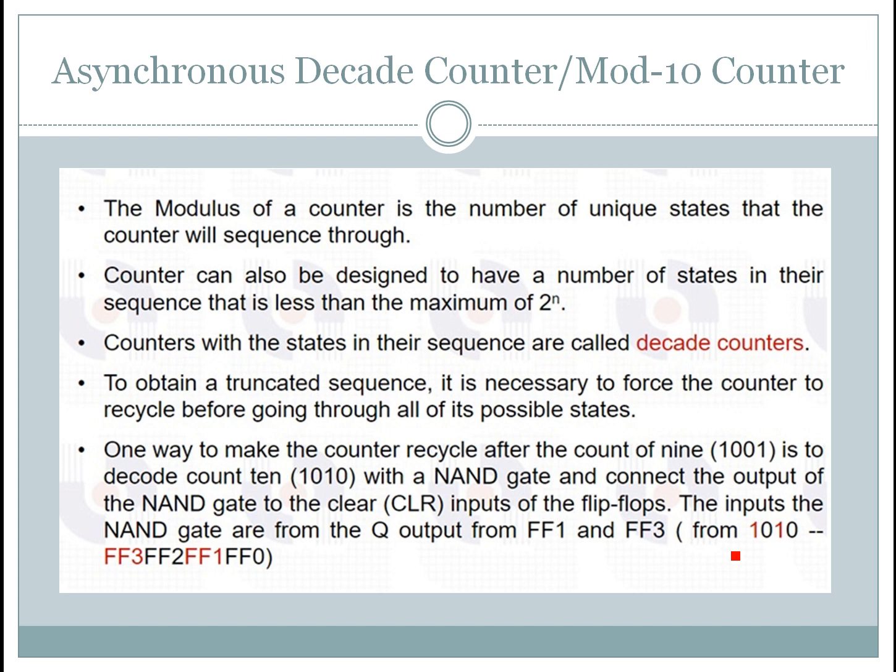So next one, asynchronous decade counter or mod 10 counter. The modulus of a counter is the number of unique states that the counter will sequence through. Counters can also be designed to have a number of states in their sequence that is less than the maximum of 2 to the power of n.